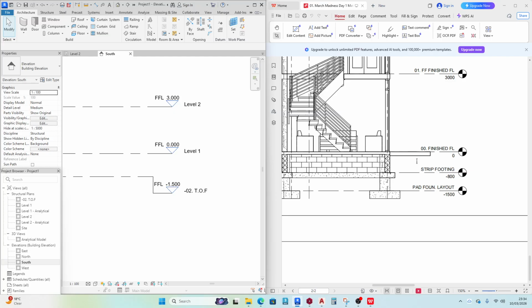If you have a lot of material, and if the client is a client of means, you can put the strip foundation on the same level as the pad foundation. Why I did this in most cases is because of what this implies: if the strip foundation and the pad foundation are on the same level, the foundation walls will need to go deeper there. Meaning you need more courses, you need more material, more cement, sand, quarry, all of that.